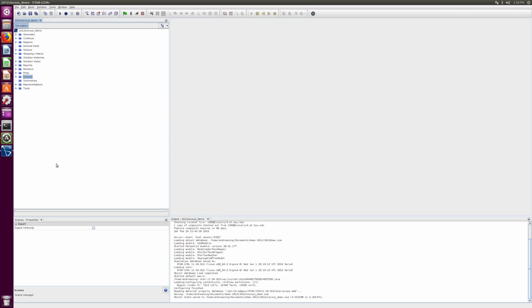So I've opened up the simulation from the last video, the Inviscid one. I haven't changed anything. I've just opened up the same one that we saved last time, because I'm going to do that same airfoil. It's a NACA 2412. Right now it's set up at 5 degrees angle of attack. We already did a grid convergence study, at least for the Inviscid flow. So I've got a pretty good starting point to move into a viscous simulation. And I just want to focus here on the changes I need to make to handle a viscous case, rather than starting from scratch again.